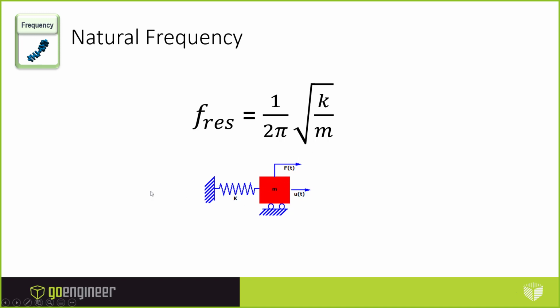This is what I'm going to use to try to calculate resonant frequencies on the basketball hoop that we'll be looking at later on. The basketball hoop is going to behave very similar to this system. In the case of the basketball hoop, the mass is me hanging on the end of it, and the stiffness is the bending stiffness of that hoop. And so we can actually use this fundamental formula to help understand that system a bit better.